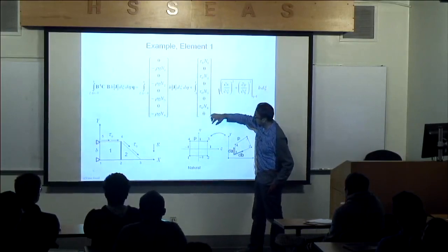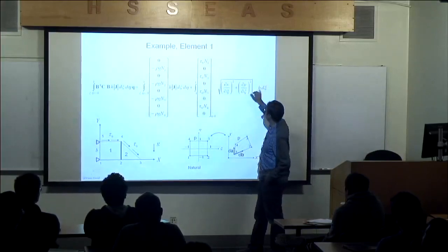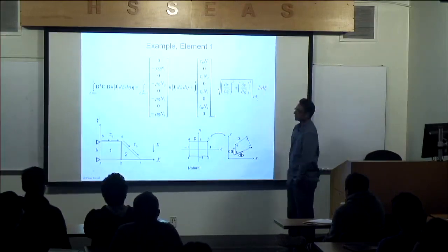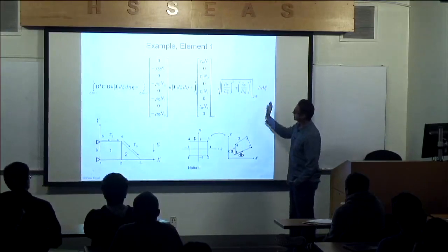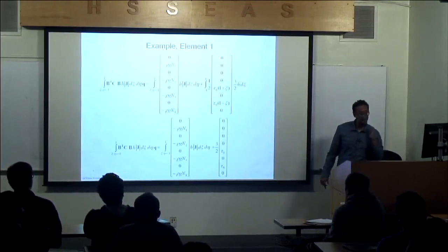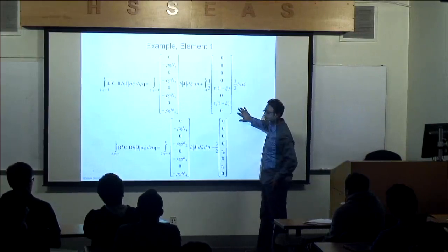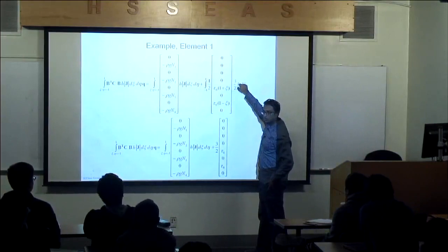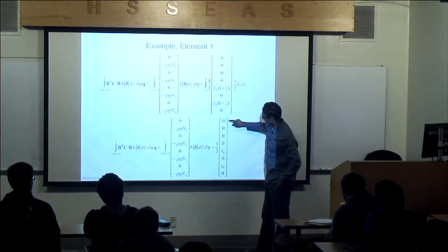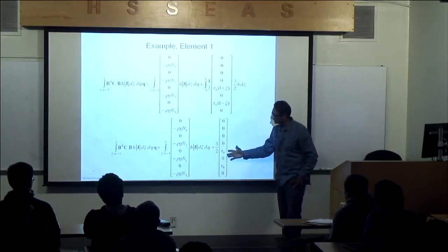And not only that, now I have a differential element here that has to be evaluated. That differential element is dC, and by chain rule you get this equation. I covered this with the heat transfer problem. Evaluated at eta equals 1. Okay? When you do that, you basically get the element formulation for this element, which is given here. Okay, so you evaluate eta equals 1, and then the square root, you evaluate eta equals 1, and then you basically get this here. And when you integrate this guy here, you get 0, 0, 0, tau 0, 0, tau 0, 0. Okay? And then you get 3/2 here.